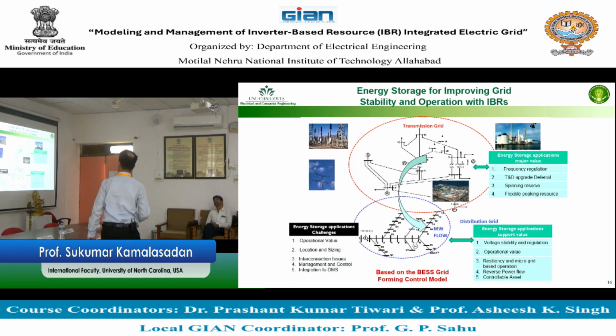So now we look into what you can do with energy storage. There was a big discussion yesterday. We talked about how you can use inverters for reactive power support. You can use energy storage for active power support. Inverters cannot do active power support. Inverters with photovoltaics also cannot do active power support, because photovoltaics will be asked to push the maximum power to the electric grid. If you ask the photovoltaic to manage the power, then you call it curtailing. Then you say, I don't want to curtail, I don't want to manage.